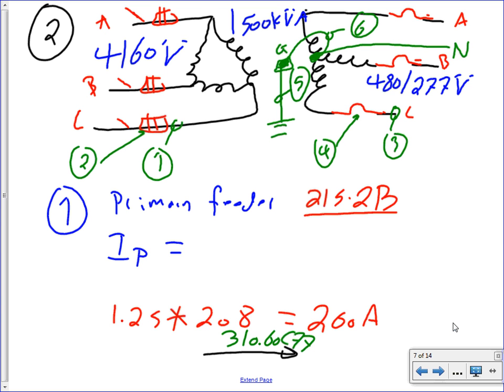Because you get 2 voltages, right? Yes, and also it's safer for equipment, absolutely. Number one, a grounded system is a better system than an ungrounded system in terms of equipment, it doesn't burn equipment on spikes. And number two, we get 2 voltages, right? You get 2 levels of voltages that you can use.